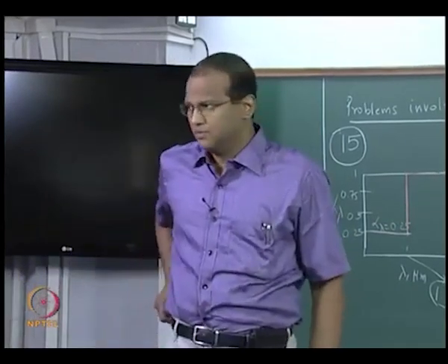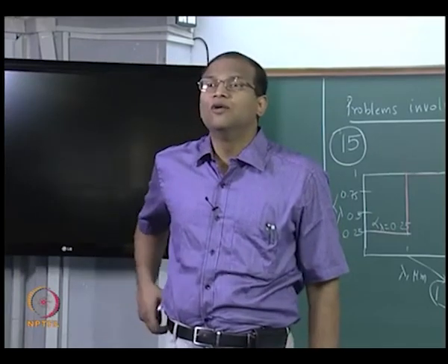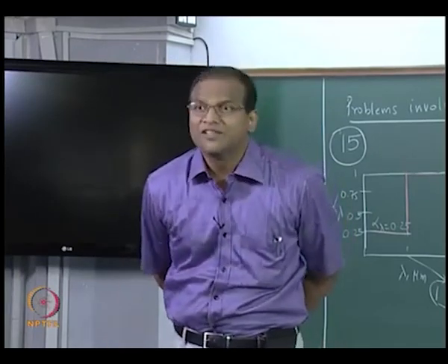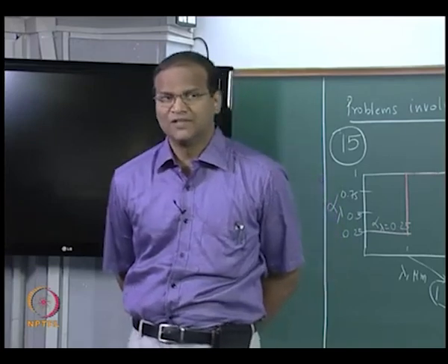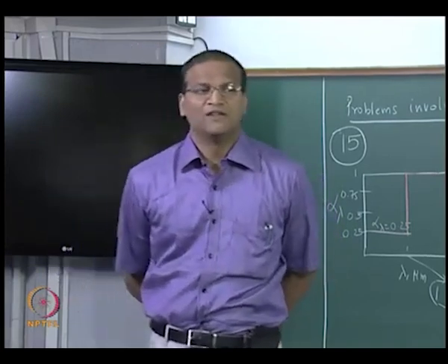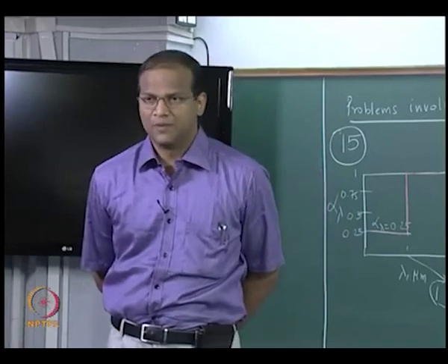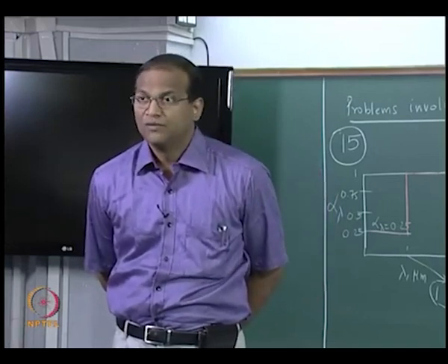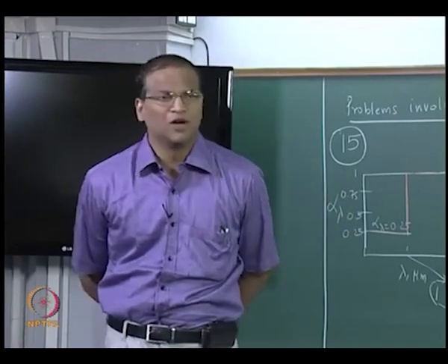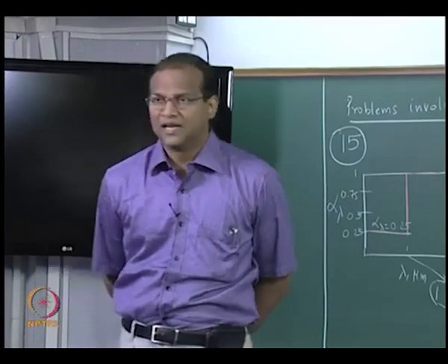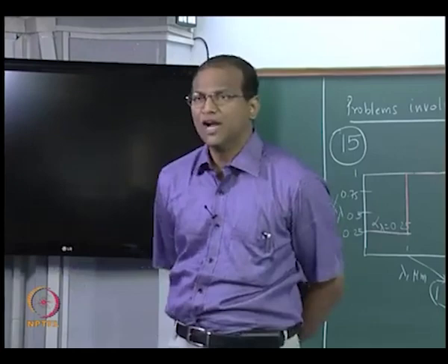Okay. That is why we are able to employ what are called selective surfaces. What is a selective surface? A selective surface is one which will have poor emission in the infrared and high absorptivity in the solar part of the spectrum. For what application do we want a surface like that? For a flat plate collector, we want high solar absorptivity and poor emission.